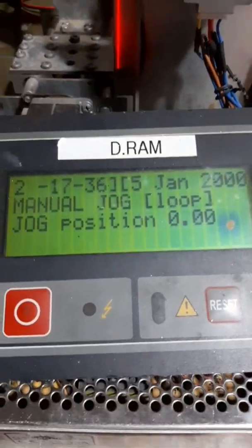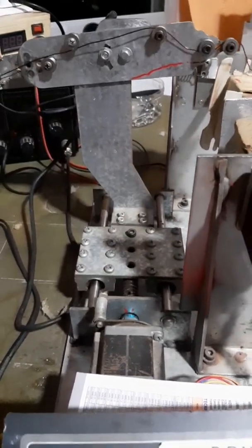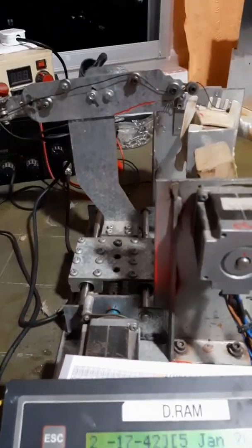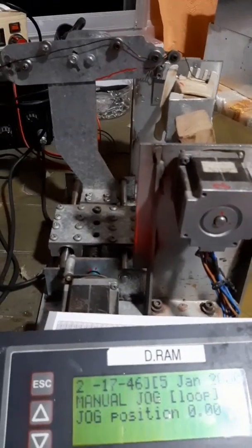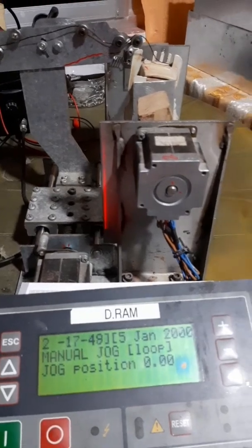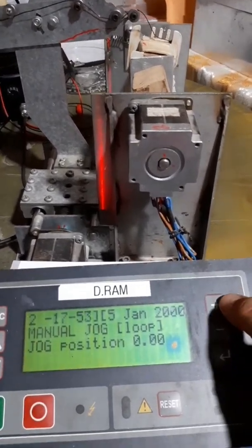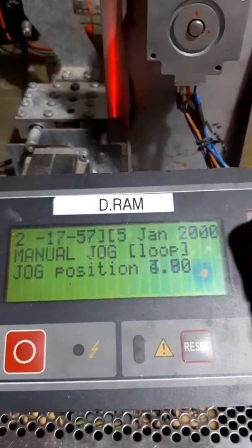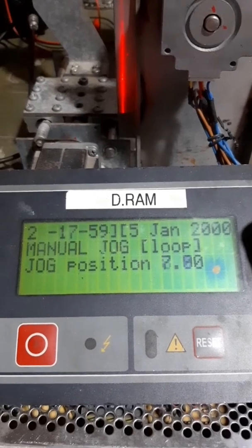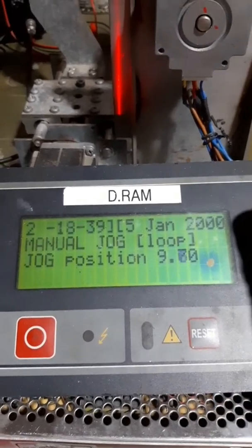Now I have 0 0, which means this is the 0 position of this axis. This machine is a CNC control. It is not like a normal type of machine. This is a CNC control, a 2 axis CNC. So I will just add some parameter value here, plus. For example, I will add 10. This is the millimeter travel. So this is 10 millimeter.